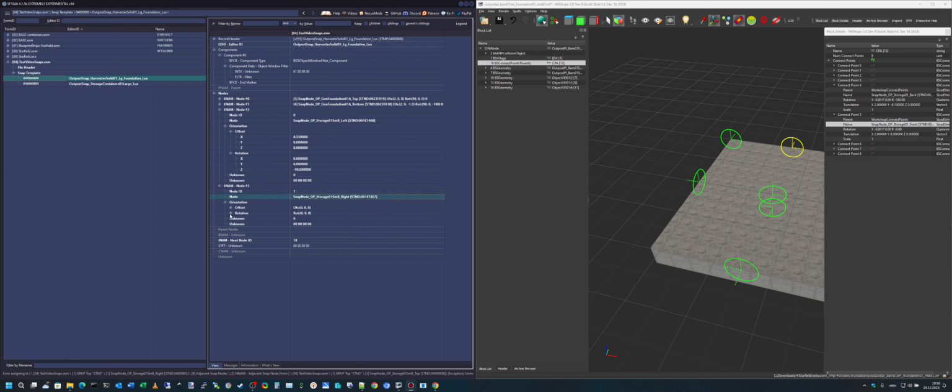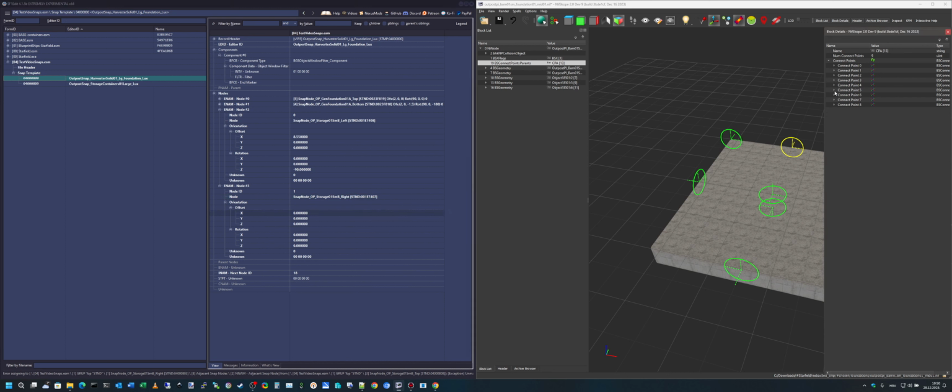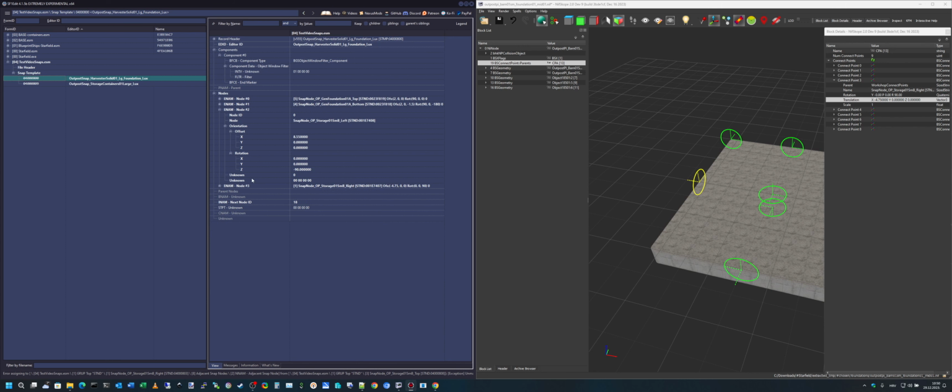And then again we have to change the rotation and offset. Here we used, which one is the right? SMB right. So rotation is 0, 0, 90. Do check that it's not negative 90, because that's opposite. And translation is negative 4.75, and other coordinates are 0. So once we add this